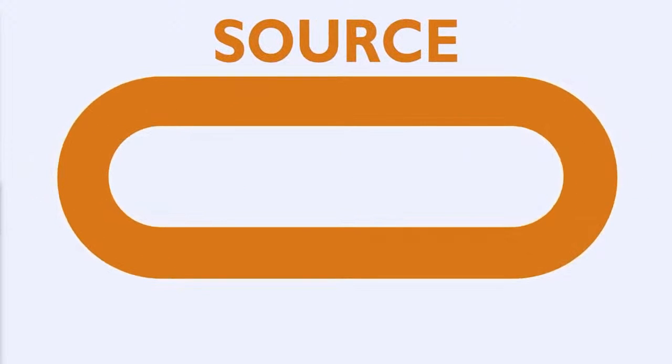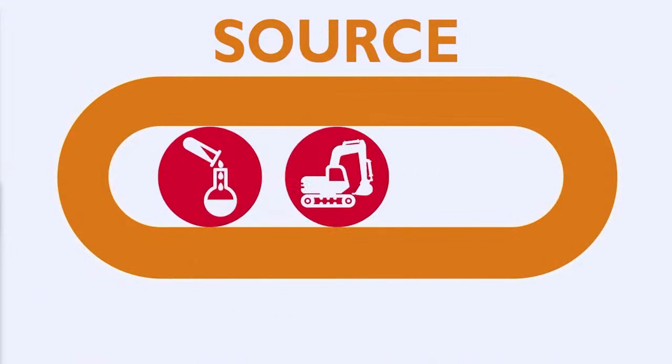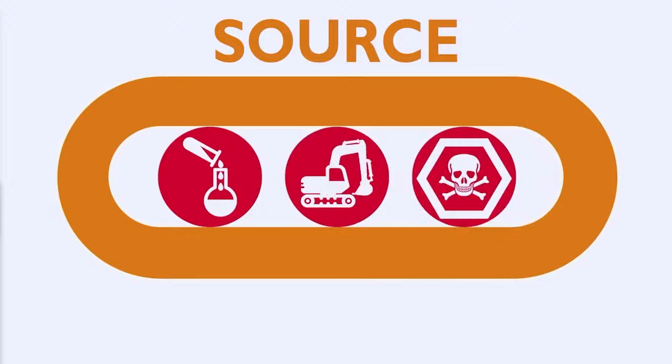Source treatment involves taking action to break the linkage at the source, the actual pollutant itself. In very simple terms, this involves achieving one of the following outcomes: destruction, neutralization, whereby the pollutant is rendered harmless through the use of some form of treatment, such as adding a degrading chemical agent or a process such as heat. Removal, which can entail either removal of the polluted soil and disposing of it off-site or extracting the pollutant from the soil. Immobilization, or trapping the pollutant by adding chemicals to solidify the contaminants, making it impossible for the liquids or vapours to escape.